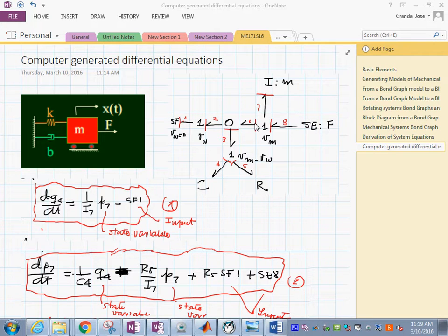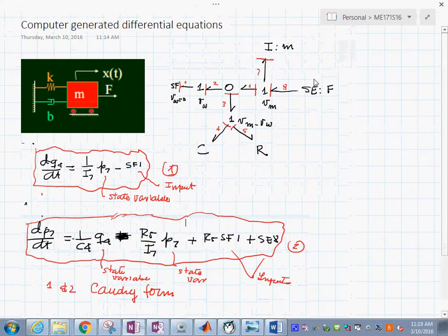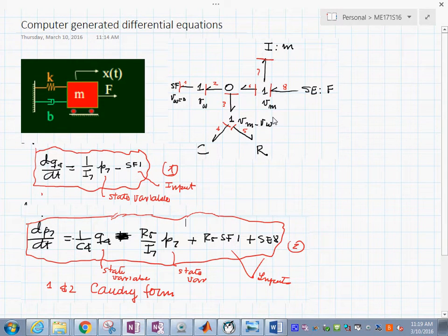So we follow the regular established procedure that we have indicated in previous videos, and that is how we actually generate this bond graph model by attaching all the elements on the one junctions, and then we use zero junctions to produce the velocity differences and attach the elements that see or experience those differences, and that way we have come up with this bond graph model.